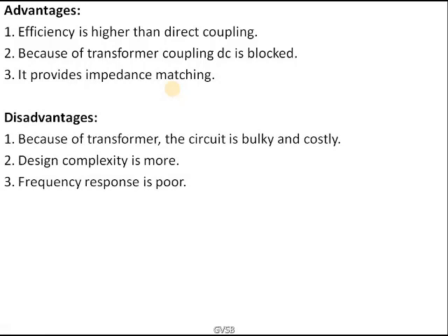If you see the disadvantages, we are using a transformer. Transformers are bulky devices and they are costly. That is the main disadvantage when we use a transformer in our circuit. The design complexity is more and the frequency response is also poor. These are all the advantages and disadvantages of the transformer coupled class A power amplifier.